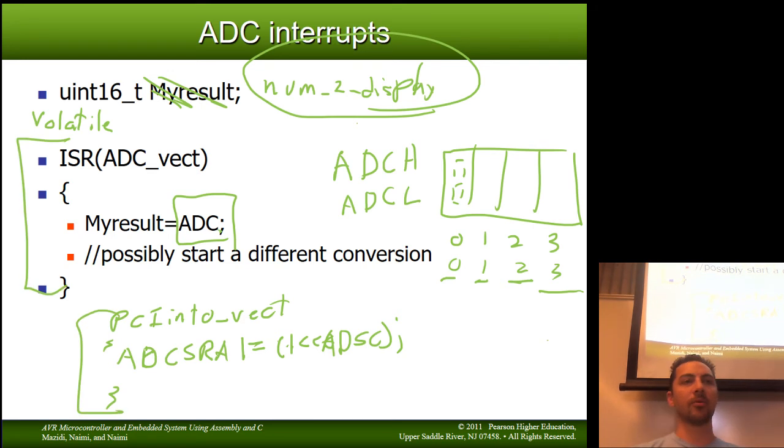So these two pieces run autonomously from the rest of the code. All right? Your main loop should just have nothing happening in it. Everything should happen inside of an interrupt for this lab. It's actually not good to put large blocks of code inside of an interrupt. You want them to be as small and concise as possible. Okay. So where are we now? So that's really all there is to an ADC. It reads an analog value and it turns it into a digital value. If you so desire, let's just go over to the data sheet for a second.